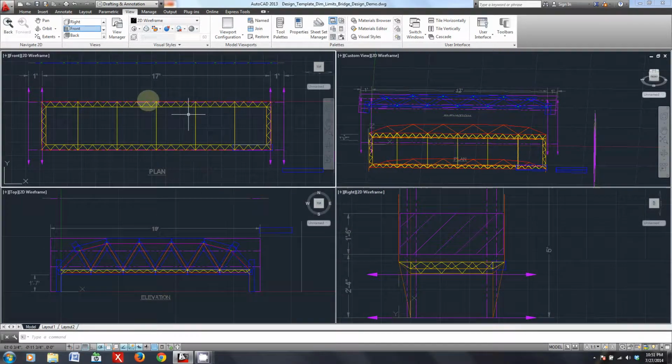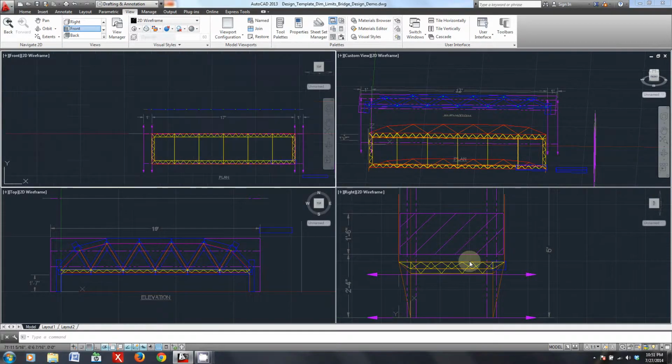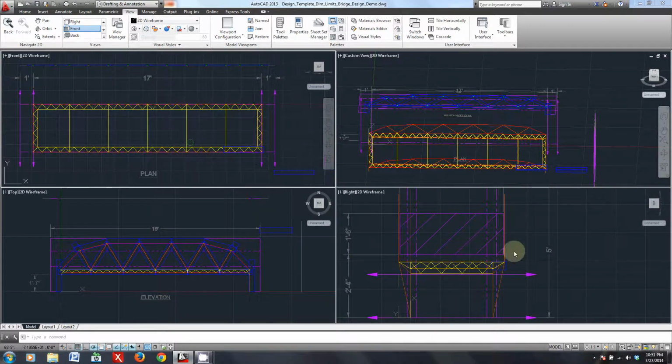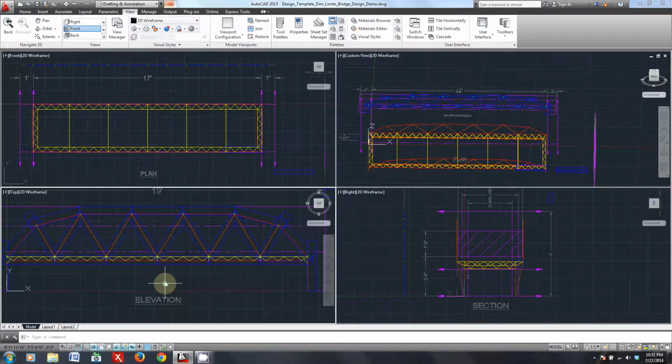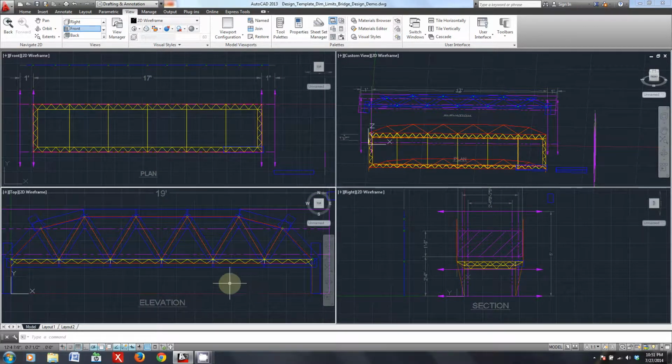So once you have that set up, you can go through, rotate in all of your dimension limitations to each of the different views, and then you can start drafting. The first place that I started for this particular design was I went back to one of our previous lessons when we started looking at 2D elevation sketching, and I took that first example that I did, which was just an emulation of what our design looked like last year. So here's the basic outline of the bridge, and I started with that purely 2D sketch, and then I decided, okay, now let's just focus on one side of the bridge.